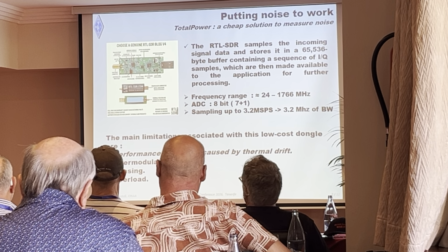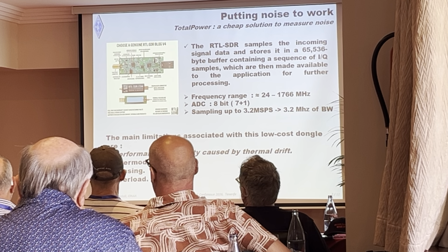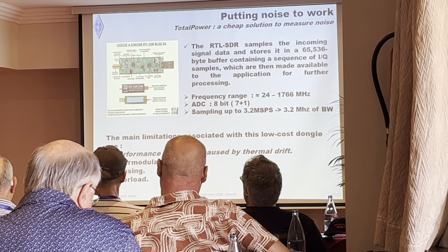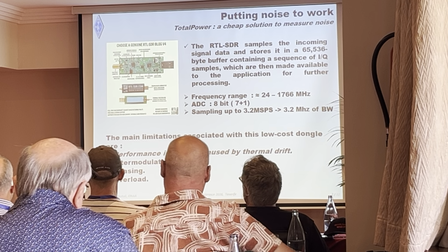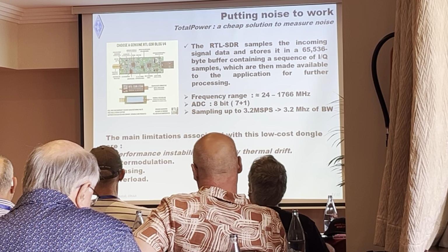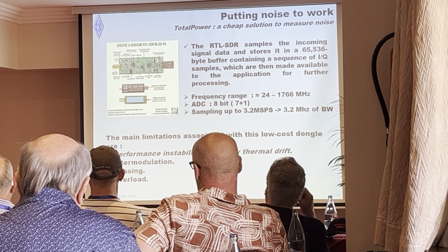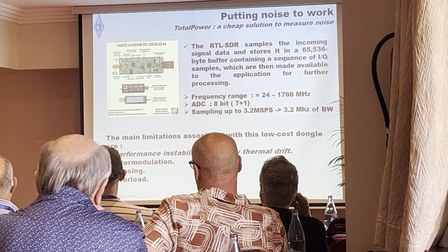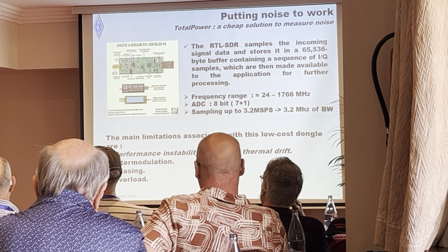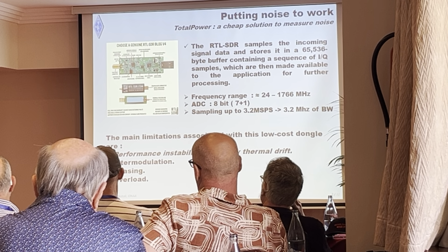But this dongle that is very, very cheap has a lot of limitations. I just listed a few here: intermodulation, aliasing, overload. But for us, the most critical thing is the performance instability caused by thermal drift. So when you attach it, this thing starts to drift, the noise is moving and so on.